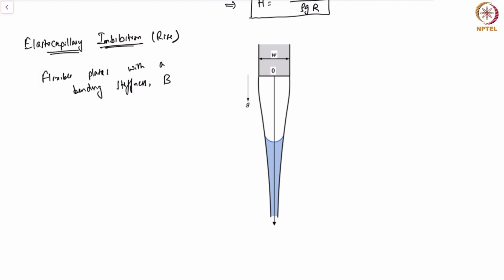But if you look at the force balance on the surface of the tube, that surface tension would basically pull everything towards itself, and therefore the normal component of the force on the walls of the surface would be pulled inwards. Okay, and recall that when we did the analysis for a droplet, a force balance approach, let's say if this was theta E, then there is a component of the force which is vertically up, that is gamma sine theta E.